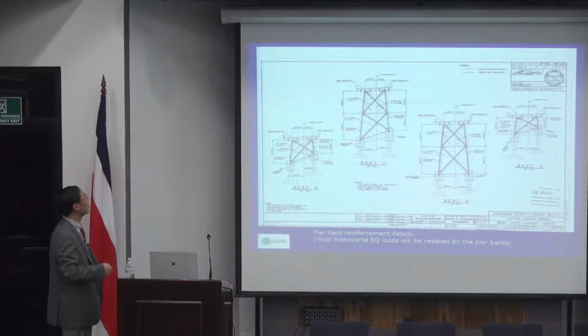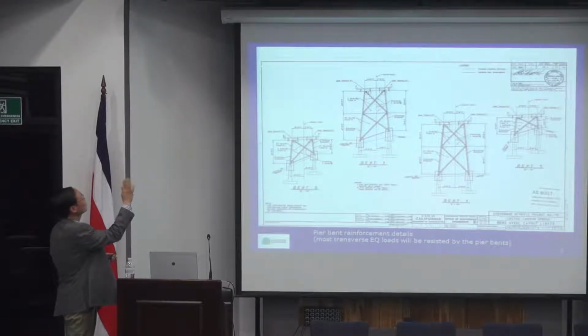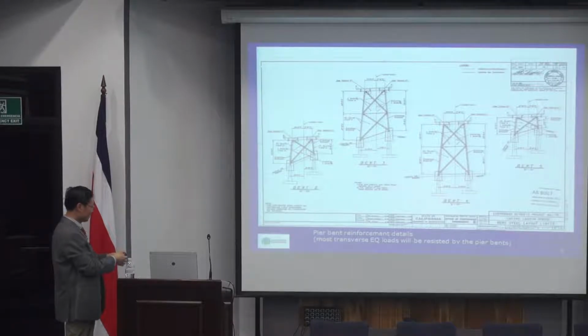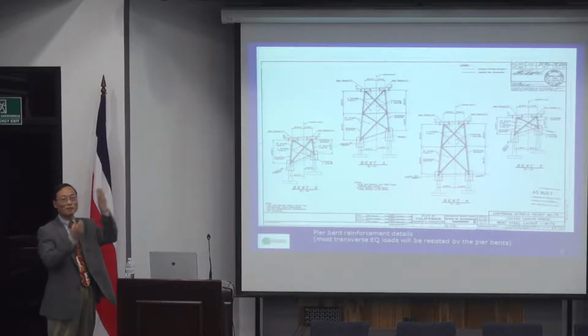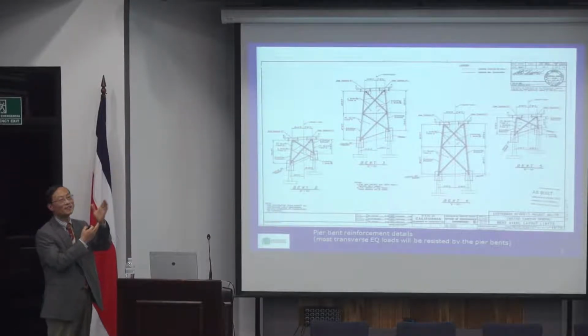Typically they have strengthened these joints and also these joints, so that when the load is applied transversely, of course, it's okay. It was designed for that. But the problem is the load, when an earthquake comes, it twists in that direction. Once it's twisted, this connection was only designed for in-plane action, so it does not have rigidity to twist.